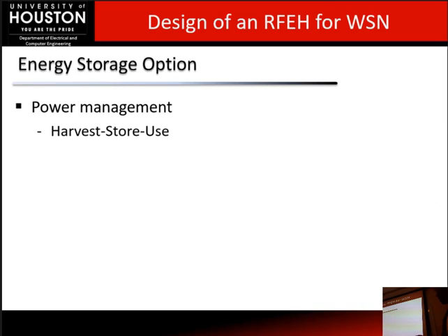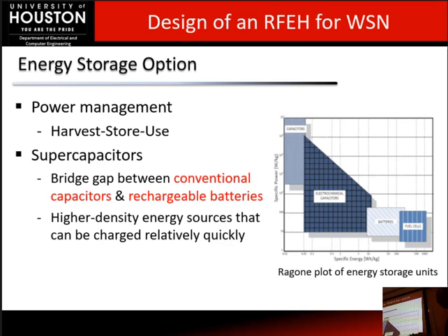So the third and last block of the energy harvesting system is the energy storage. There are two ways, as I said earlier, to manage the power harvested. One is called harvest, store, use. The other is called harvest, use. In this part one, I will only focus on harvest, store, use. And the energy that we harvest can be stored in either a supercapacitor or a rechargeable battery. In my research, I focus on supercapacitors.